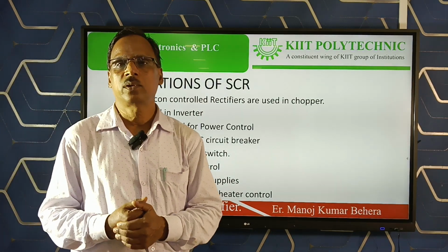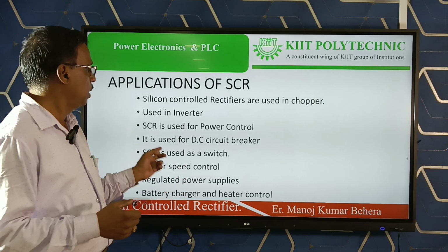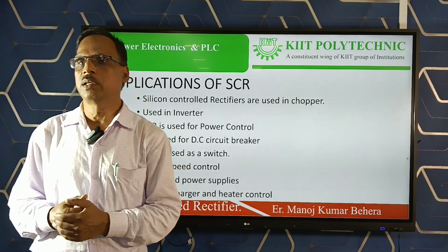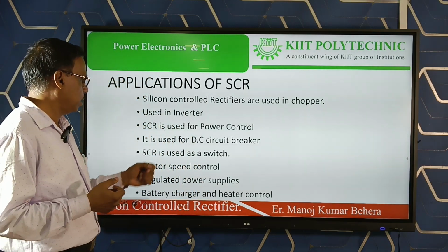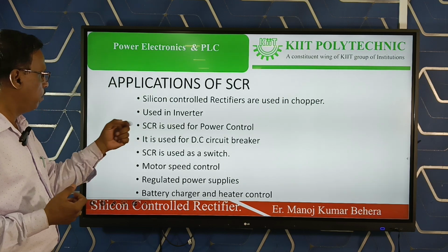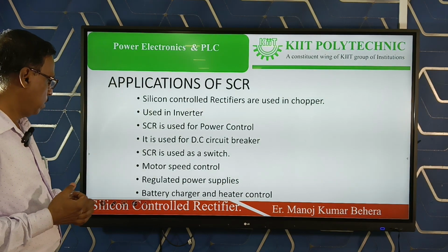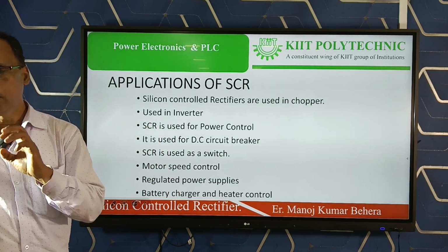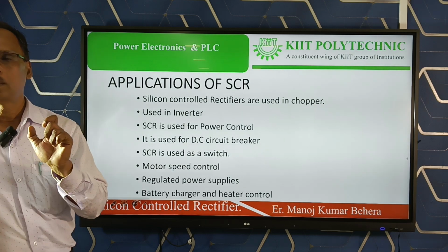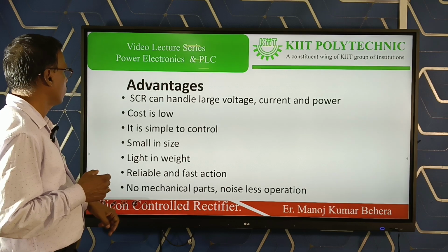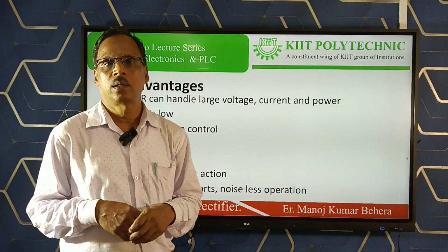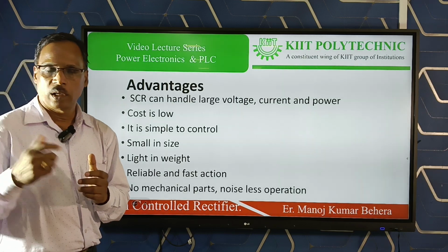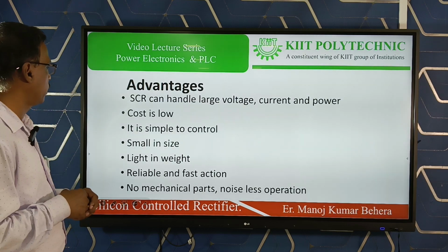Next, what are the different applications of SCR? SCR is used in inverters, choppers, power control, battery chargers, and UPS. All these devices use SCR. What are the advantages of SCR? SCR can control very high voltage and operates at rated frequency.